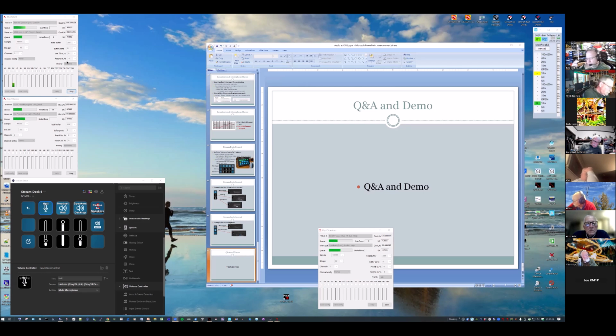And I'd recommend doing it with the headset on, right? So you're into the radio, press your push to talk, so you're listening to your monitor. So you're monitoring yourself coming out of your radio. That's what you're going to hear when you're actually contesting. You're going to hear that slight delay in your headset. You want to minimize that, and to minimize that, you end up stressing the computer a little bit. So there's a break point where, if you go too far, you'll get choppy. But if the default works for you, heck, just use it.